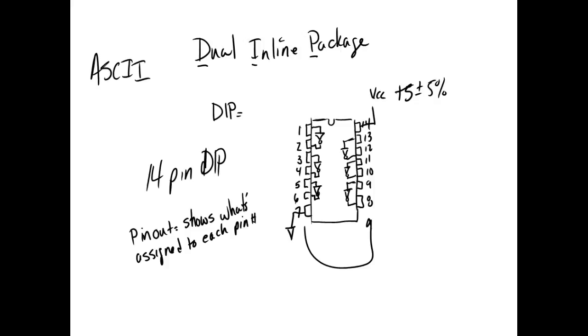So can you see, when you get yours, the little identifying notch on there, looking at it from the top? The first pin on the left is pin 1. Then it comes down the left-hand side, goes over, and comes up. No matter how many pins are on the DIP, this sequence of numbering is the same.